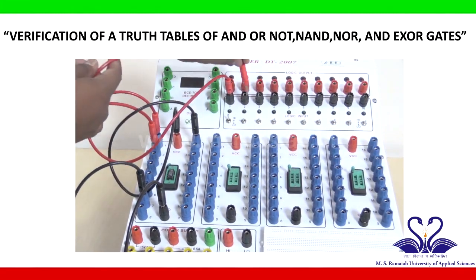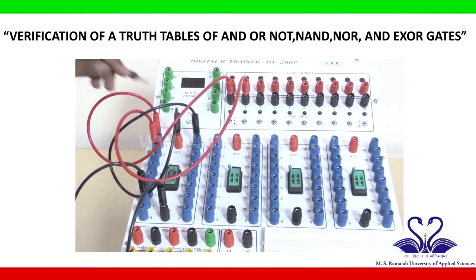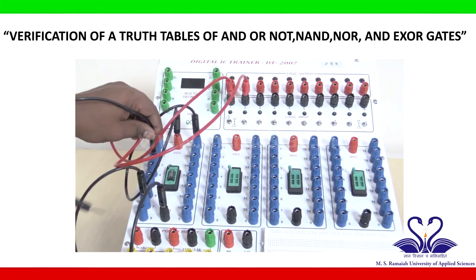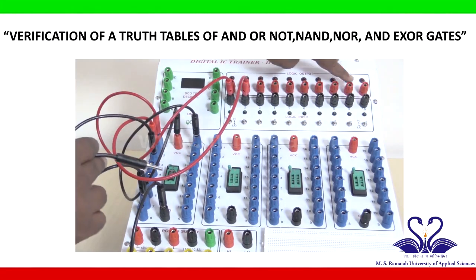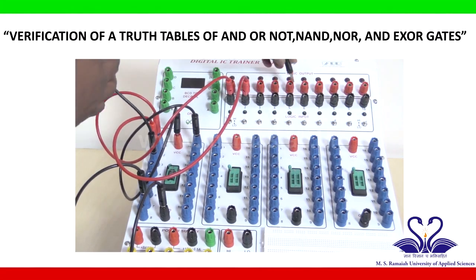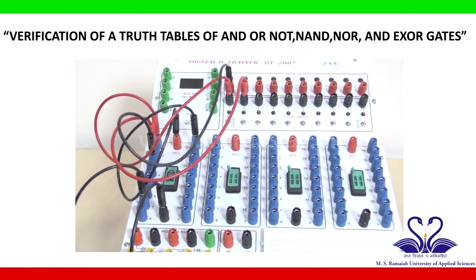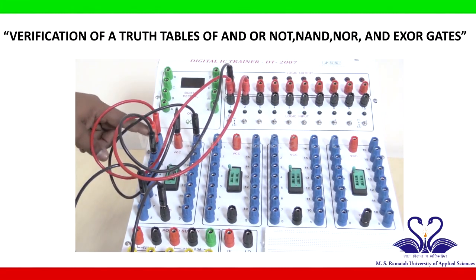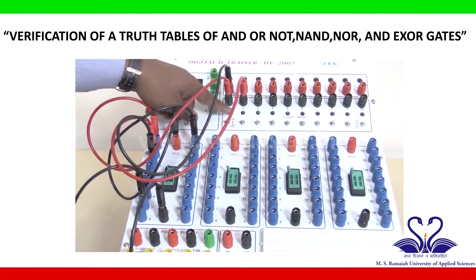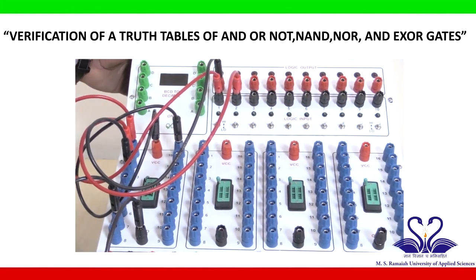So pin number 2 I will connect to one more input, and pin number 3 is connected to output. So this is pin number 3, I will take a patch card which is connected to output. Here are the outputs, you can choose any one. So let us take this output, I will connect here. Okay. So now I have chosen one AND gate, 2 inputs and one output. So turn on the IC trainer kit.